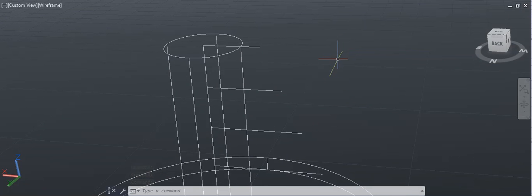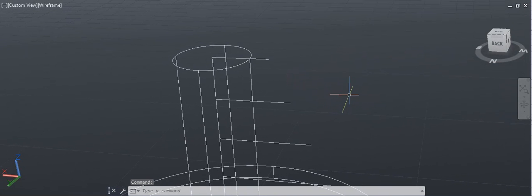All right. So far so good. One of the important things is, once this is created for the turbine blade, we're trying to create one turbine blade. After that, we're going to make multiple copies. But there's a process, okay? It's a spiraling process. So those lines, except the first one, need to be rotated at a 30-degree angle. The 3D rotate command is a good command, but I suggest only the rotate command. The 3D rotate commands are not useful or practical in this case. So I'm going to go with just the rotate command, okay?